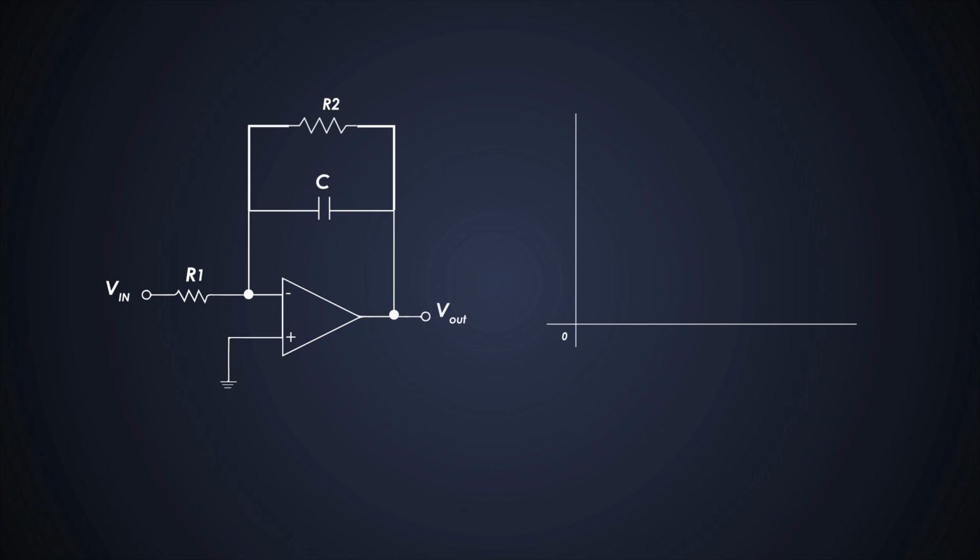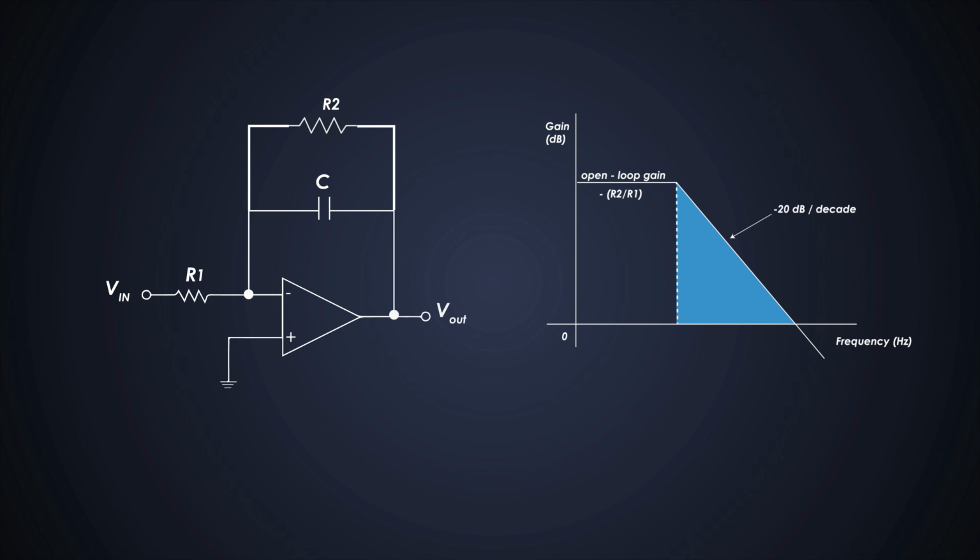This is the frequency response of the circuit. Basically, it shows how output will behave when there is a change in signal frequency. On the y-axis, there is the gain at the output, which decreases as the frequency increases. Well, this feedback resistor plays an important role here. At higher frequencies, it works as the integrator. And these are the formulas where we can distinguish these so-called higher frequencies. So the input frequency must be between these two.